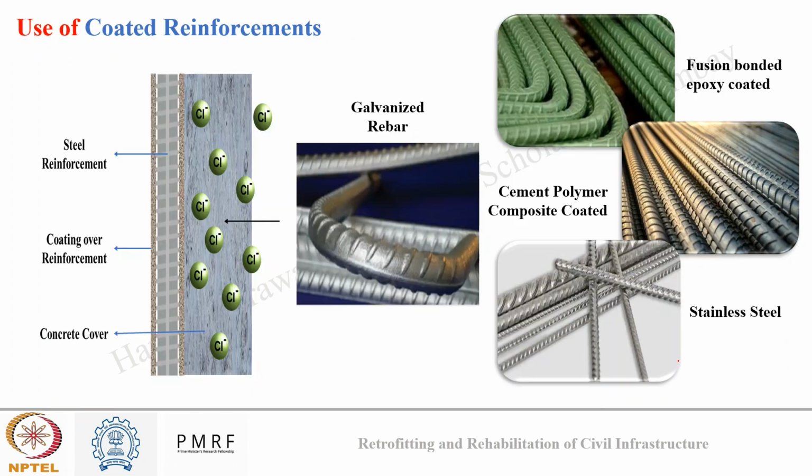Okay. Finally, the corrosion damage can also be delayed by using coated reinforcements. Now, this is not a repair technique, but more of a method which can be carried out prior to construction. So it's not like when we see cracking in concrete, we will remove the rebar completely and place coated rebar. No, we can use them from the start, and what they will do is form a physical barrier over the reinforcement, which will hinder its interaction with the external ions. Now, this is different from the barrier created by the corrosion inhibitor, because that was a chemical barrier and this is a physical barrier.